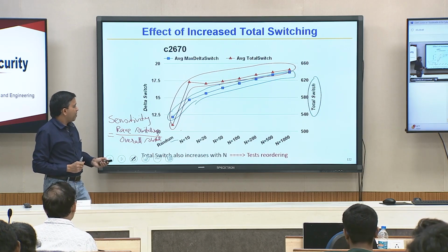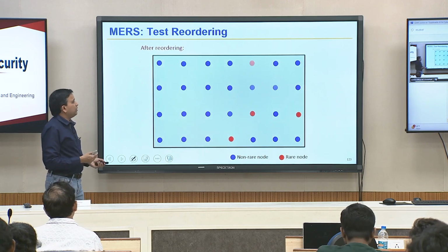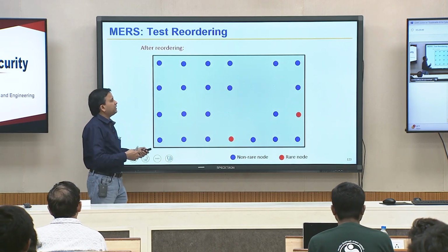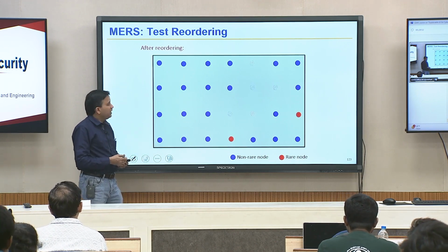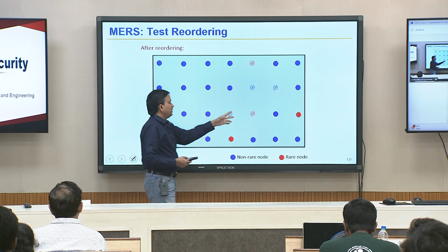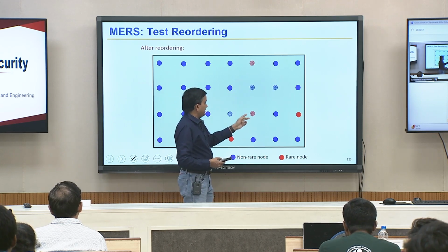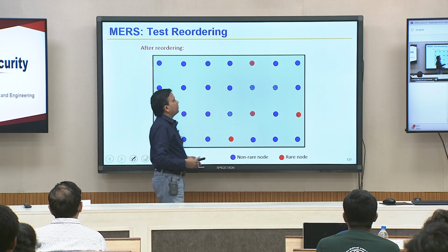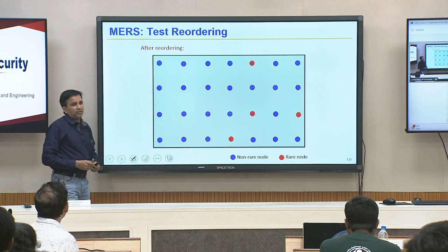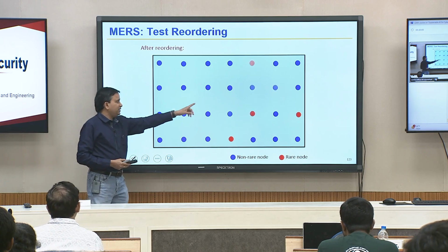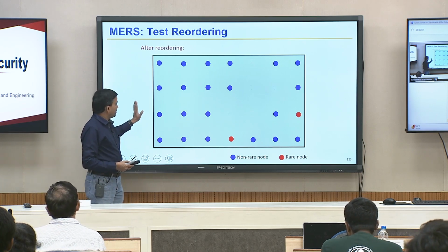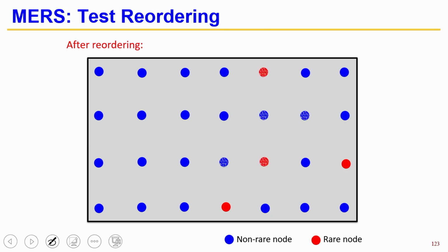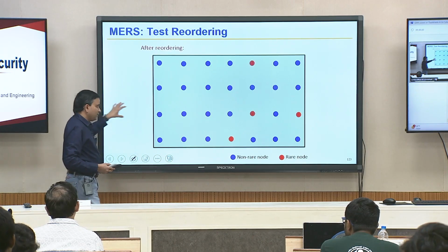So, now it just turns out that in that work we were able to reorder certain tests without knowing why it worked. It did work, which is analogically this: Trojan circuitry signals flipped and also some of the original design signals flipped. Now, in reality you realize this picture is not possible, because to go from input to output, it needs to create an event in at least one of the paths. Here, as if I am showing there is no activity anywhere in the design except in that region, that cannot happen. It is going to have some activity on some path.